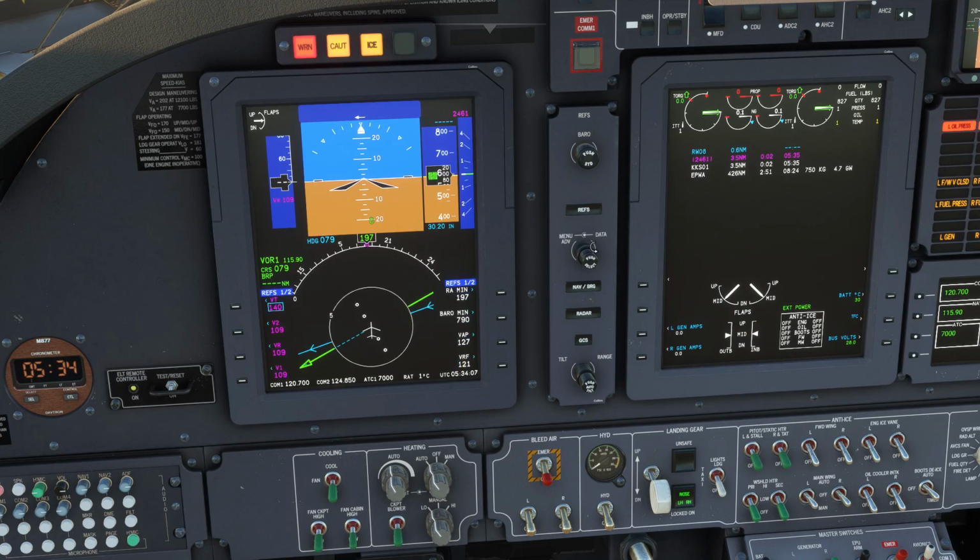Press it again and you got your options for PFD, so pressure in inches or hectopascals, metric altitude, which you can change, and then you'll have it in meters, and that's useful when you're flying to Russia or post-Soviet countries east from Poland, because they very often stick to meters rather than feet.